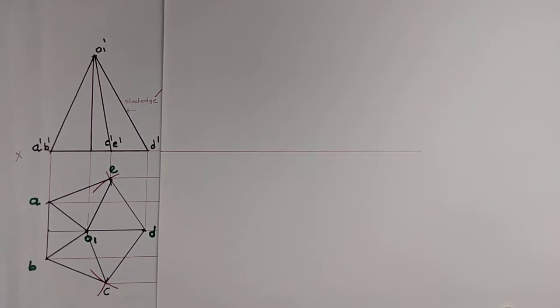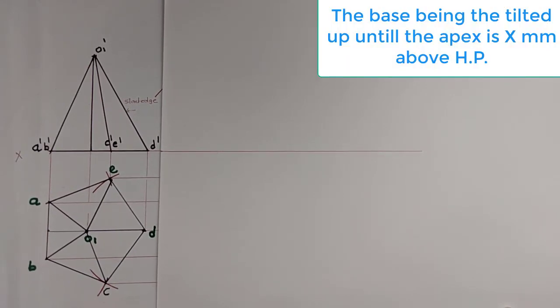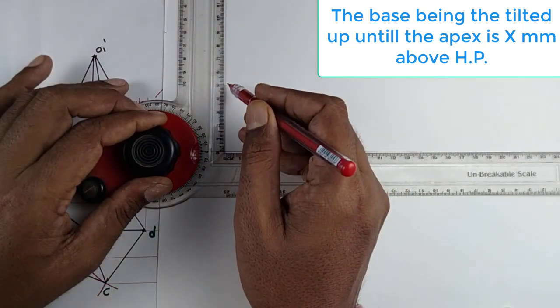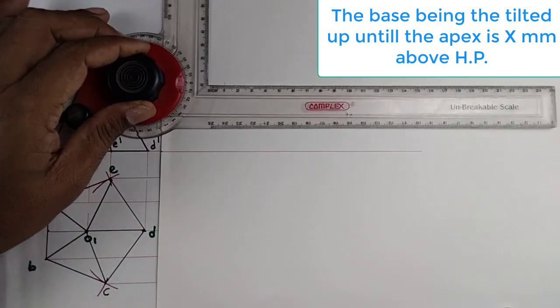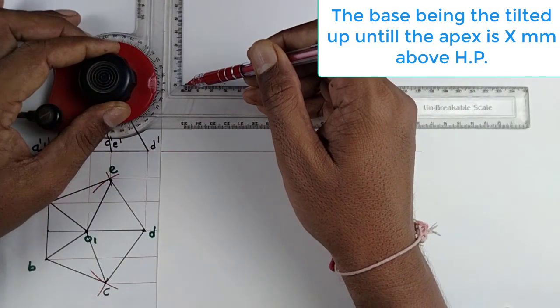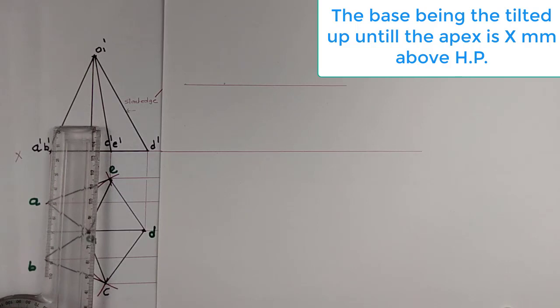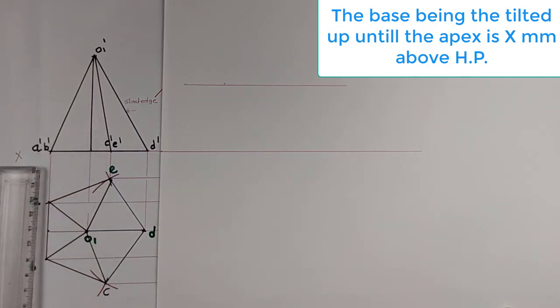Now friends, in the second stage, the statement of the problem says the base of the pentagonal pyramid is being tilted until the apex becomes 50 mm above HP. So for that, first I mark 50 mm above the HP. Then we create the locus. On this locus there is our point O1 dash.